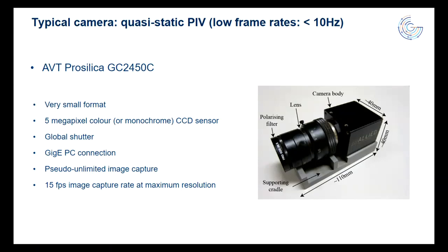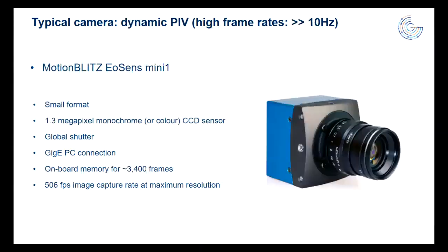And this is really good for quasi-static problems, right? All of these dynamic people here, like Yanis with shakers, it's not really the camera that they would want, but for most of the stuff that I did, this was ideal. And in fact, now we've bought a modern equivalent of this at Cambridge that has 12 megapixels, is USB 3 instead of Ethernet connection, but it's still very similar, frame rates of about 30 frames per second. So good for quasi-static tests.